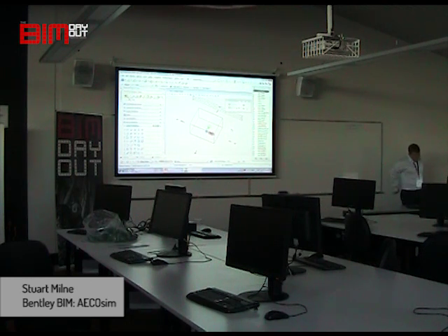Okay. Now, in order to create our very first space, say at the ground floor plane, what we need to do is rotate our view to the top view, so we can look down on that object and flood the space that finds the edges. To do that, up here is our view rotation tool. If you hold that one down, you'll see number 2, this is top view. Click on that, the whole model rotates to an exact top view.